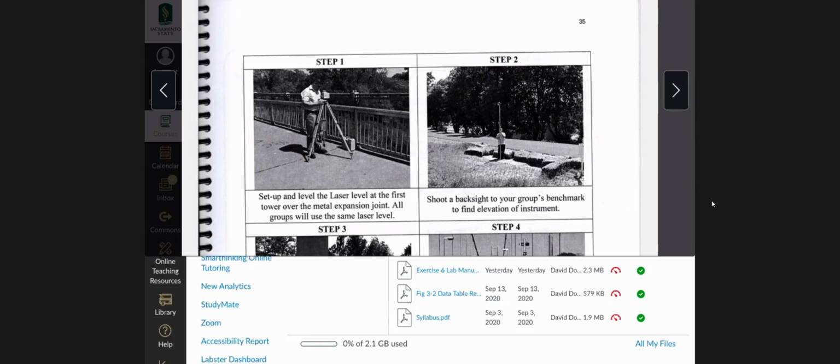If you remember, we didn't talk about it much in lab 3 or 4, but there are 2 ribbons on the face of the leveling rod. One of them is 0 at the bottom, and it increases as you go up. If you turn it around and you extend it, you will see that you have a 7 at the top of the rod, and the numbers get higher as you go down the rod, which is backwards of what you would do normally.